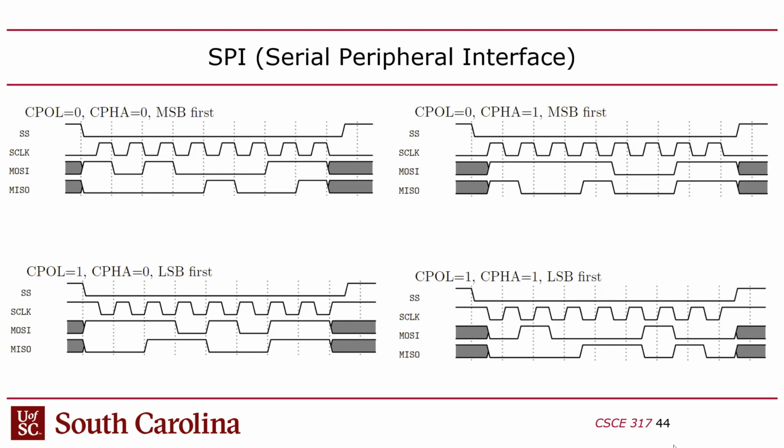You might say, what about clock level? We'll talk about that in I2C. I2C uses the level. That's another protocol. But in SPI, the assumption is the data is read on the edge of the clock. The clock's edge is what captures the data, what triggers the capturing of the data. Okay?